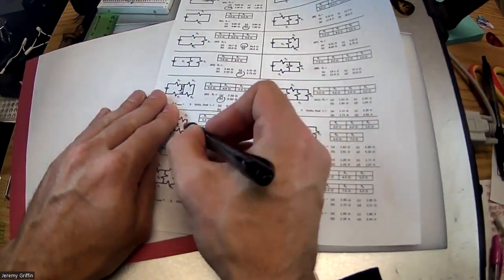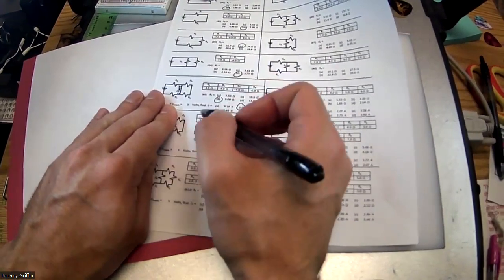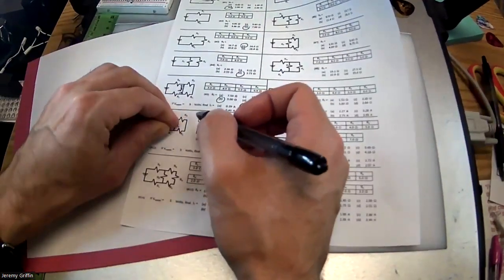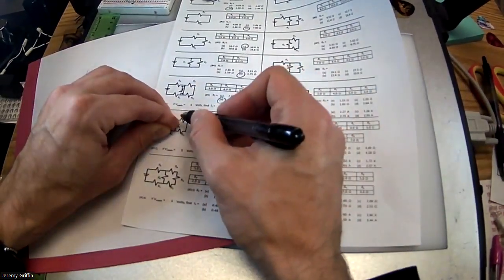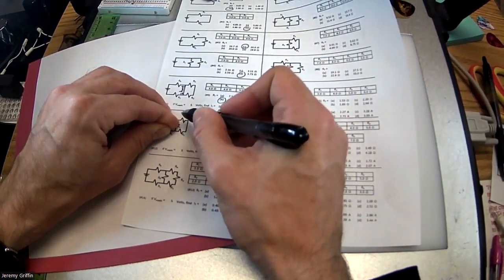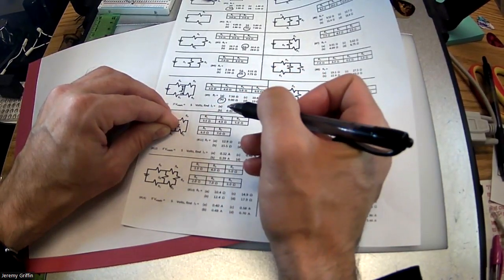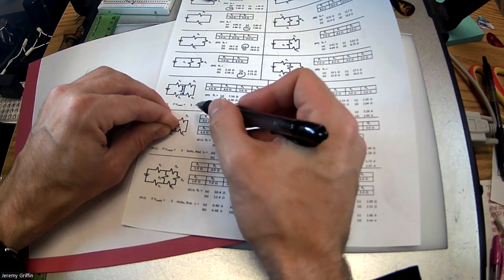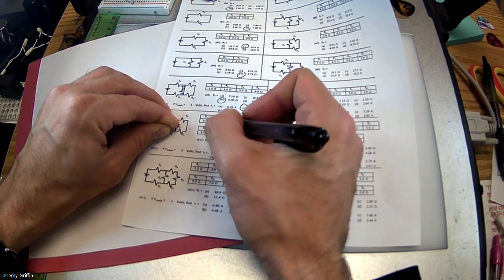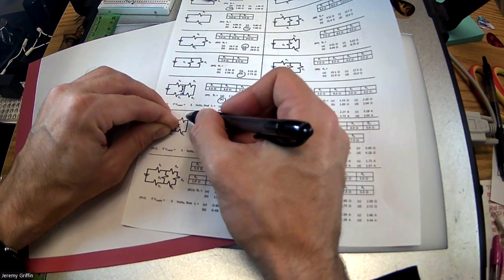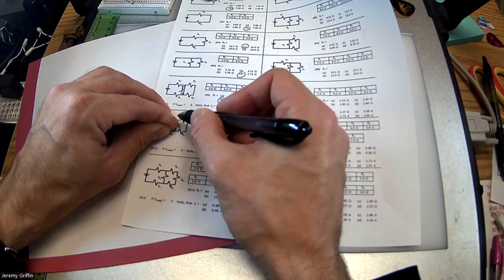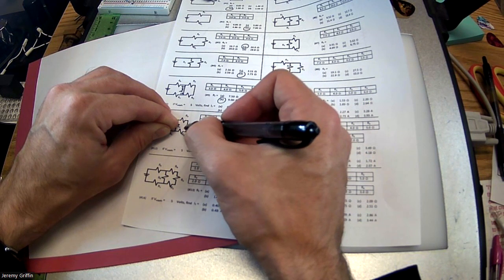So I'm looking at these two resistors. Now, if I'm only focused on that part of the circuit, I'm just going to ignore everything else except for those two. Are these two guys in isolation in series or parallel with each other? Series, because whatever current happens to fall on this part of the circuit has to go through one after another sequentially.